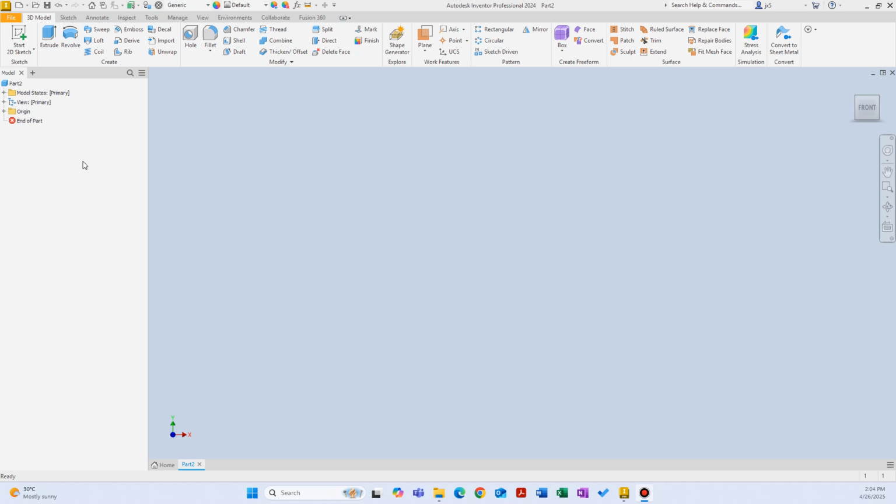Actually, sometimes you can create the same part with extrude and with revolve as well. Sometimes it just requires more clicks, so one of them can be the most efficient way to design it. But of course there are certain applications that require a certain feature, extrude or revolve. So which one is the best for your design? That requires some practice, and as we do more exercises you will have a better understanding of that.